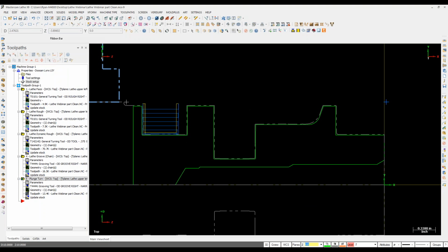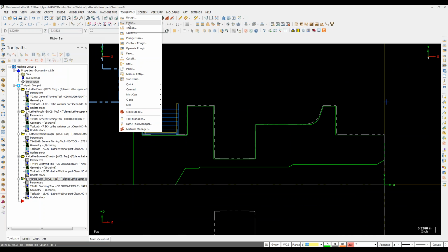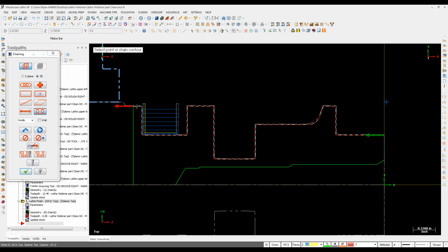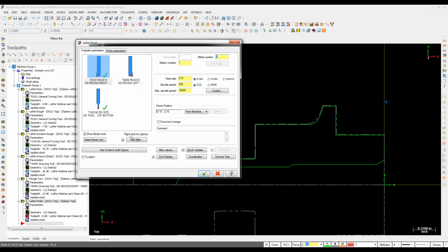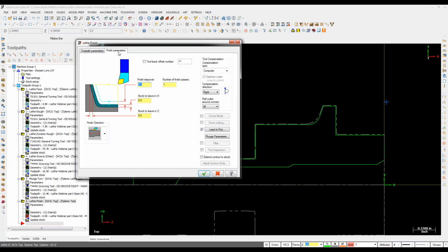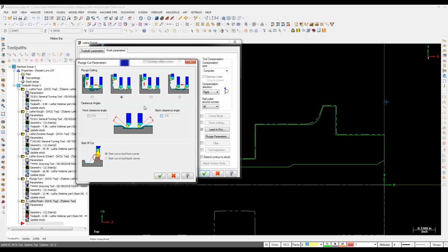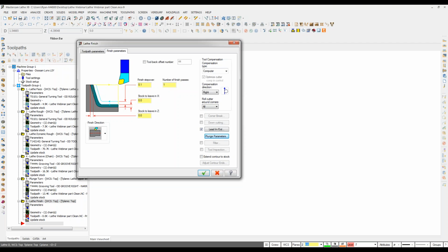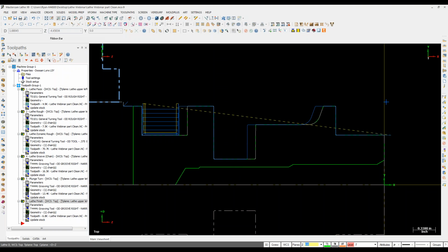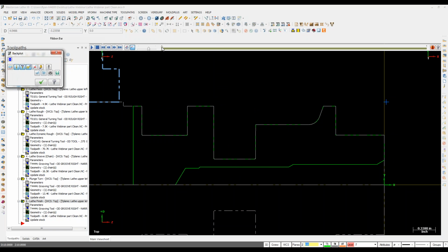Once that is good to go, the last thing I want to do is a finish on this one. So I can go ahead and say toolpath finish. I'm going to do my whole entire part from point to point, and I'm going to use a grooving tool, that way I can do all directions on here. I'm going to tilt a little bit on my lead in, lead out. I'm going to extend it by, we'll say, a little bit more to make sure it's good. And of course I'm going to plunge down in that direction. So again, that last tool path would look something like this.